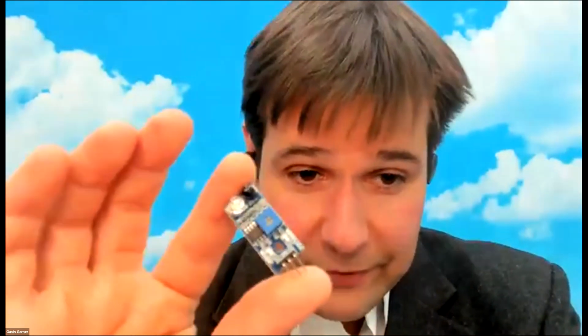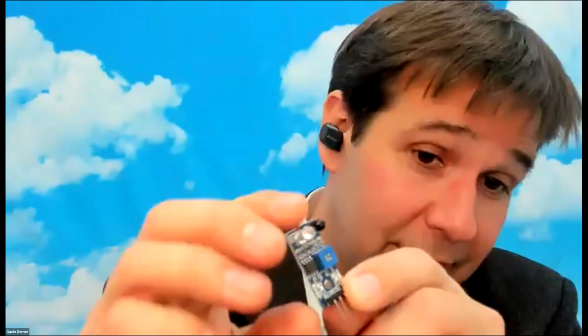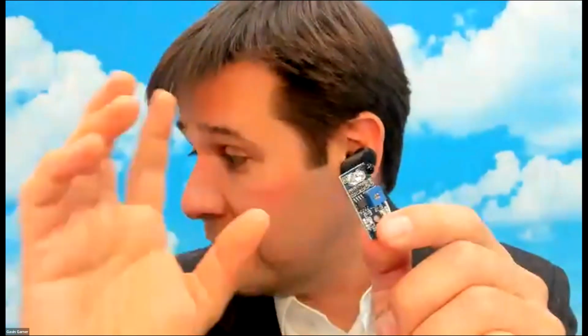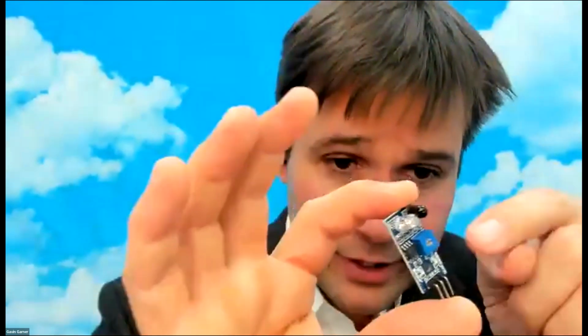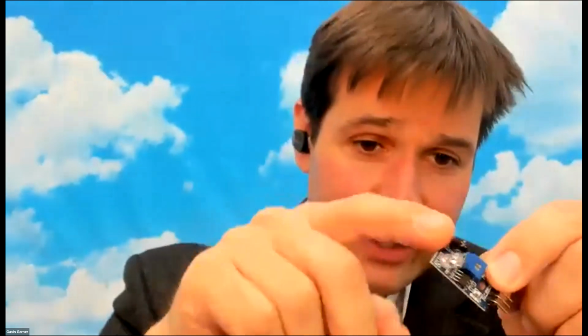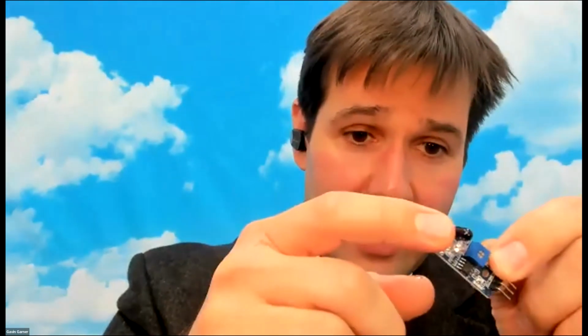They've got all different flavors of these, but they basically have a little tiny comparator integrated circuit chip on these. And you've got ones for measuring soil moisture, ones with photoresistors on them. So they just come pre-done, and you've got a potentiometer that you adjust the threshold voltage for the comparator. In this case, it's an IR emitter and the clear LED, and then it comes back to the photodiode, the darker one. And so I use these a lot.